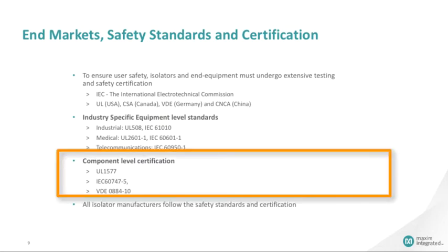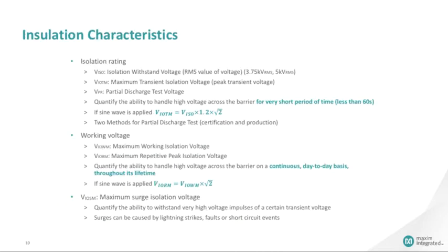Component certification standards apply to specific components that can be used in a variety of applications. These standards define the required tests, sample size, and preconditioning. They may also define terms and information that are required for the datasheet. During normal operation, the stress voltage across the isolation barrier is limited by the maximum system line voltage.